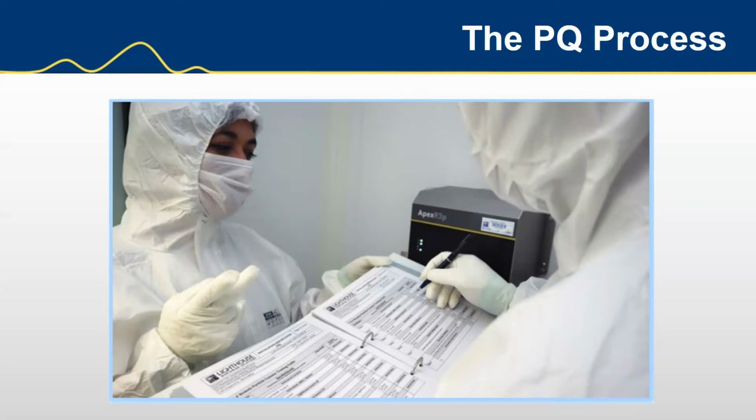Now, when manufacturers take time to plan qualification projects, they sometimes ignore important considerations. Companies often fail to take a science or risk-based approach based on product and process knowledge to define the extent of qualification. And for the most part, they redo the OQ protocol and call it good. Nah, please don't do that. That's a major mistake and a missed opportunity to get to know how the system operates and the capacity of the system in a real working environment before you go live.